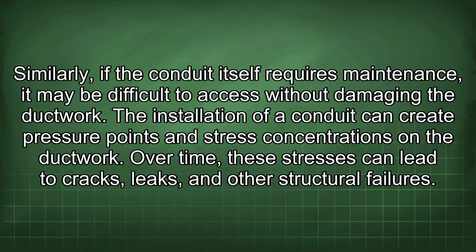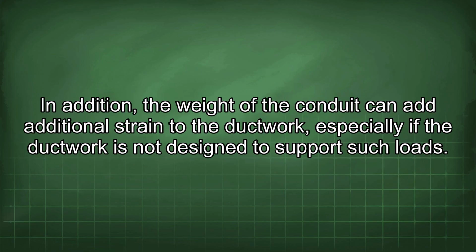The installation of a conduit can create pressure points and stress concentrations on the ductwork. Over time, these stresses can lead to cracks, leaks, and other structural failures. In addition, the weight of the conduit can add additional strain to the ductwork, especially if the ductwork is not designed to support such loads.